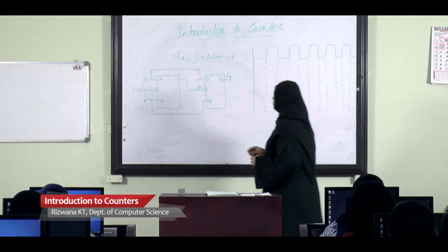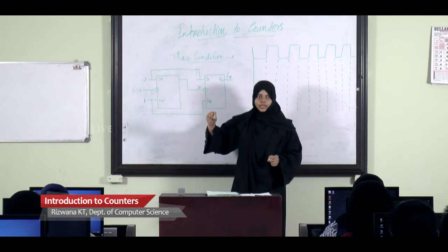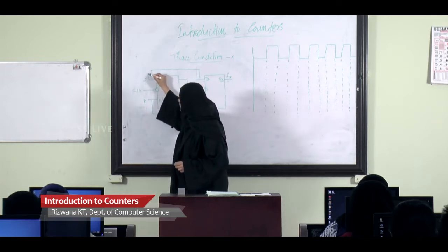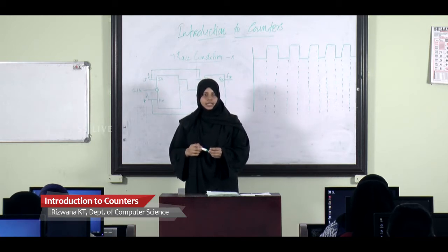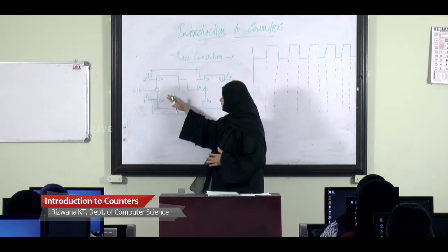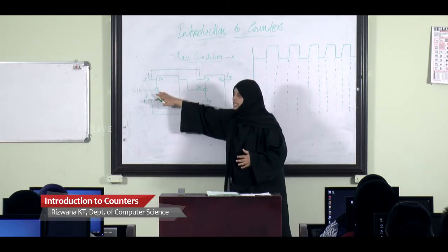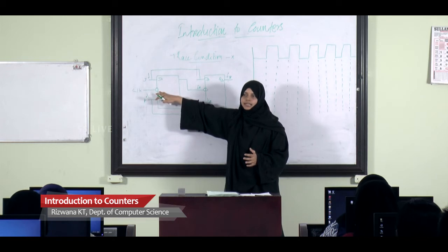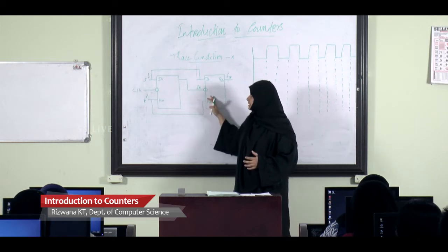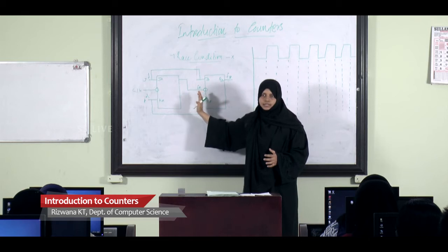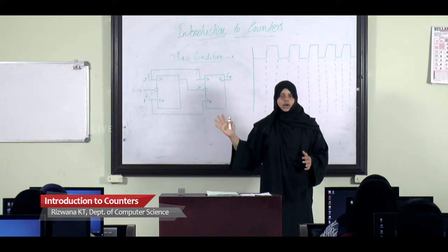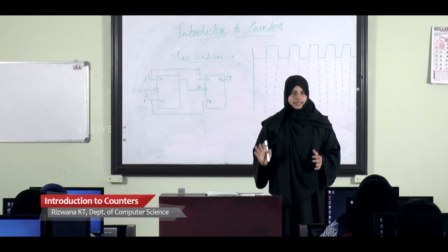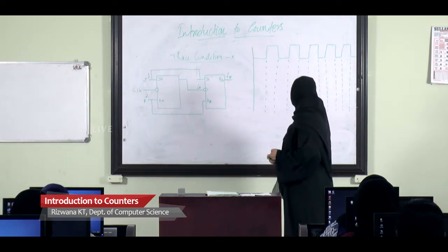The major drawback of the JK flip-flop was that when we provide the input J equal to 1 and K equal to 1, the race condition arrived. Now we overcome the situation by giving the clock pulse in negative edge triggering mode. This connection is known as the master-slave connection. We are using the edge triggering mode, and so we are setting this in a toggling mode. Is that clear now?